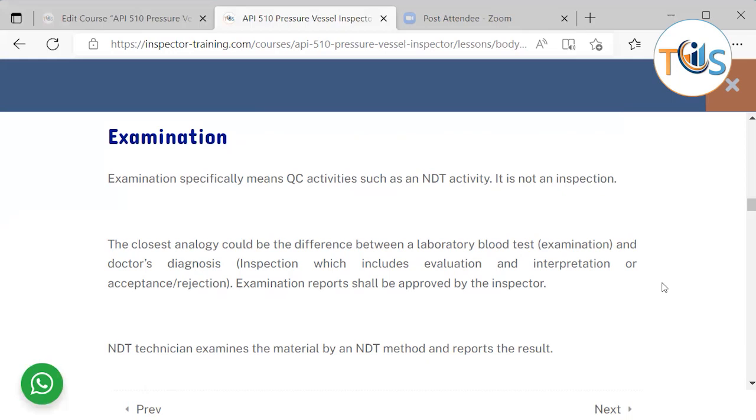So he finds out the type of discontinuity and its location, and when he does the interpretation, if the NDT examiner is allowed to do that, he compares the discontinuity he discovered, based on size, type, and location, against the acceptance criteria, and notes in the report whether it is acceptable or rejected. If it's rejected, then it needs to be removed and that part repaired, or the whole thing needs to be discarded, depending on how they decide to go about this.